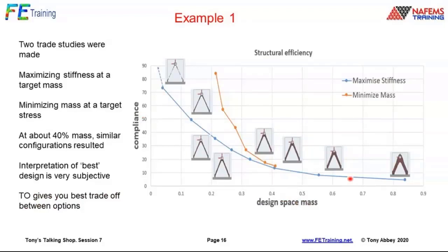Now, if I maximize stiffness, minimize compliance, I get the blue curve. And what I'm interested in now is the variation. Up here, I've got chunky structures which are over-designed. Down in here, I've got structures which, basically the dashed line there, fails. It's a structure which can't hang together, and in fact, the optimizer can't get continuous material across there because it just ran out of enough material there. So somewhere in here is going to be my design which is strong enough, stiff enough, and very efficient.